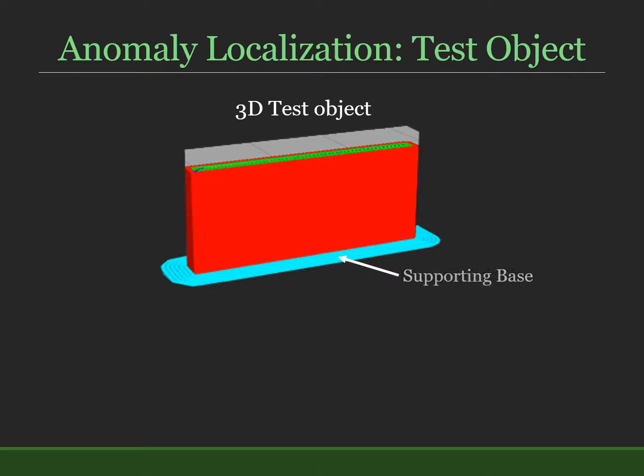For testing the accuracy of the digital twin for detecting the anomalous signals that can possibly cause deviation in the quality of the product, specialized test 3D objects, as shown in the presentation, are used. We have simulated the variability of the environment by varying one of the physical twin system parameters such as beta 1, beta 2, etc. In our experiment, we have selected flow rate as one of the beta parameters. Flow rate should be maintained for uniform deposition of the filament while printing in Fused-Deposition Modeling 3D printers. However, due to sudden slippage, faulty filament, etc., the flow of the filament may deviate from its nominal value.